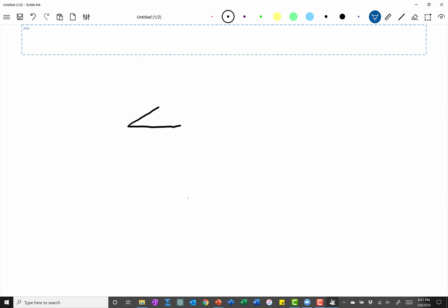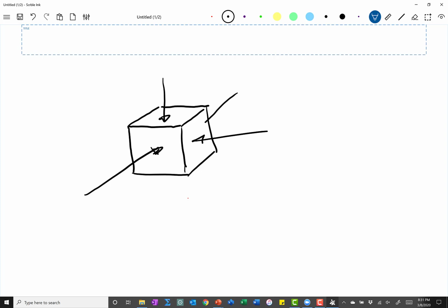You have to remember that we have to think about these things in 3 dimensions now. So I'm going to draw a cube of soil, and this cube of soil has stresses acting on its 6 faces. Whichever axis has the largest stress, let's do axial compression. In axial compression, the vertical stress is the largest, so we'd assign that as sigma 1. And then we'd assume that the 2 horizontal stresses are approximately equal. So for axial compression, sigma 2 is going to equal sigma 3.